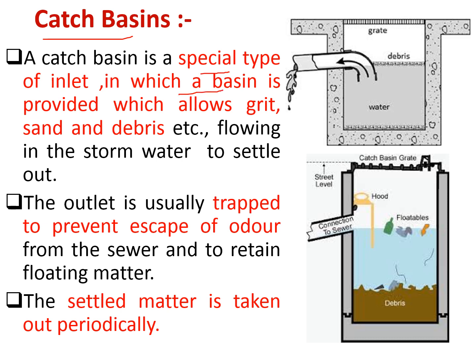It's a kind of inlet only, but it is a basin which is provided with an additional facility, and that additional facility allows the grit, sand and debris etc. flowing in the storm water to settle down. Here you can see that some time period is provided, so that all these debris and suspended solids which are settleable in nature will settle down, and water may be collected from some higher elevation.